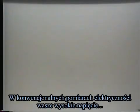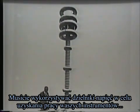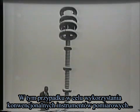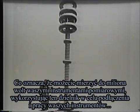Okay, in conventional measurement of electricity or high voltage, you have to use voltage dividers in order to get your instruments to work for you. Now, as the voltage gets higher, these voltage dividers get quite large, and in this case, in order to use conventional measuring instruments, this thing is more than 9 feet tall, and it's good for less than 1 million volts. So that means you can measure up to 1 million volts with your regular measuring devices by using this divider to bring it down to where your instruments can work with it.